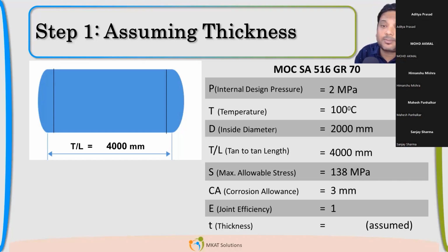If you remember the very first class about basics, if there is steam service, the chances of vacuum happening are very, very high. It always happens in offset condition unless that vessel is designed for vacuum. The operation itself being vacuum is very rare. So in all other cases, you are not designing for vacuum. The vacuum happens because of offset condition, and offset condition will always be different from your normal operating.